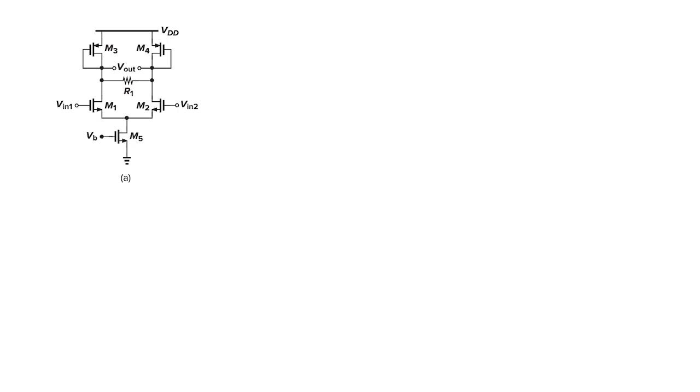So hello, today we're going to discuss the differential amplifier. Rather, I will explain how to solve different kinds of problems in the differential amplifier. So this is the first problem: how you will solve the differential amplifier. This differential amplifier's differential gain is nothing but Vout divided by the differential input difference.